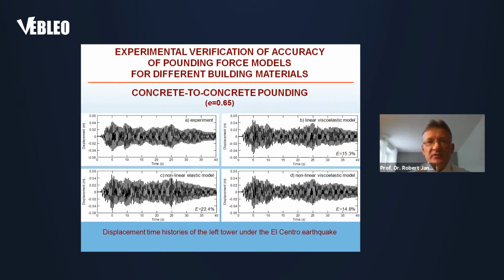These results are for the concrete to concrete pounding. On the left top, we can see the result of the experiment. And then we have the displacement time histories for different models: linear viscoelastic, nonlinear elastic, and finally the nonlinear viscoelastic model. These time histories are for the El Centro earthquake.